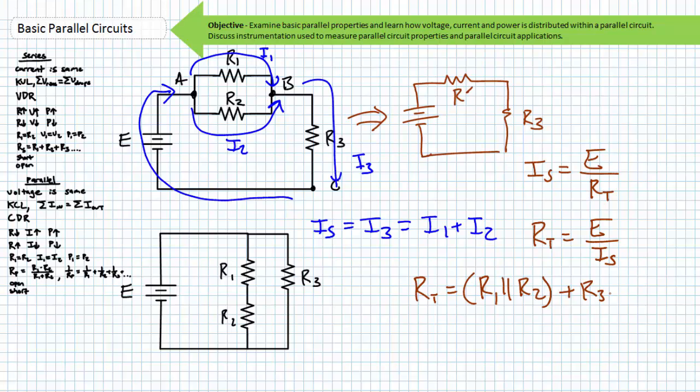Although this could be done, current through R prime should equal current through R3, and the voltage drop across R prime plus the voltage drop across R3 should equal our total applied voltage. Any further simplification beyond a purely series circuit with two elements is like taking apart your car to find a quarter under the seat. Just look under the seat.